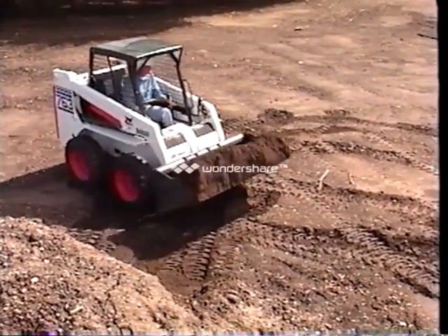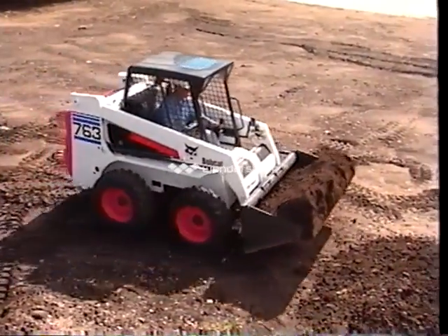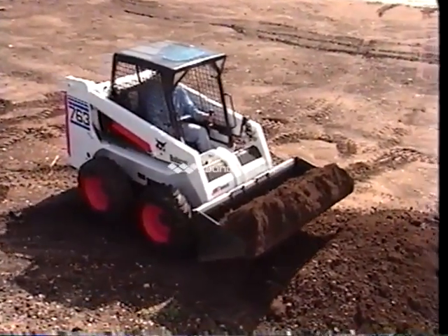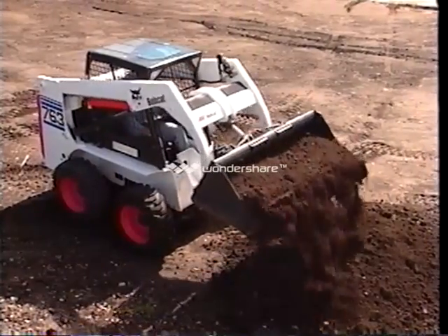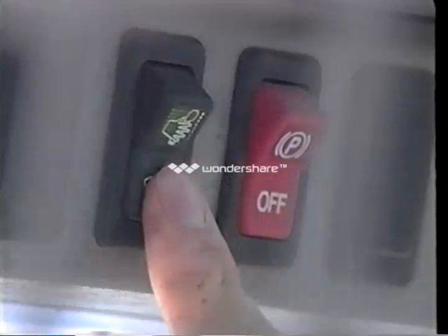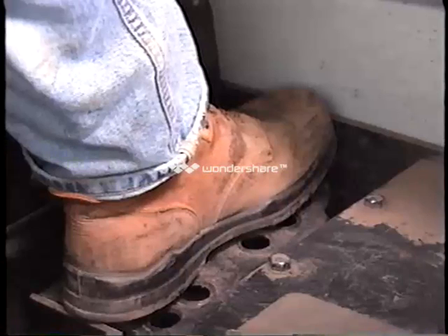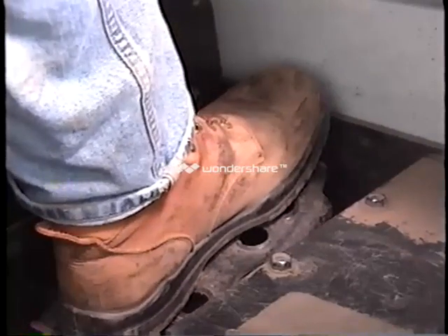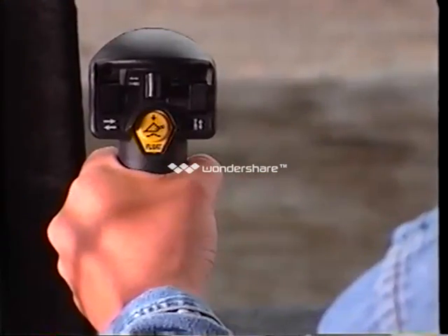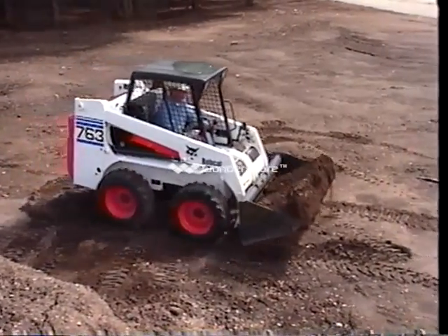Choosing between hand controls or foot controls on some Bobcat skid steer loader models is now as fast and easy as pushing a switch, thanks to the new Advanced Control System. Available as a factory-installed option, the Advanced Control System, or ACS, allows the operator to select between foot controls or hand controls of the lift and tilt functions by using an instrument panel mounted switch.